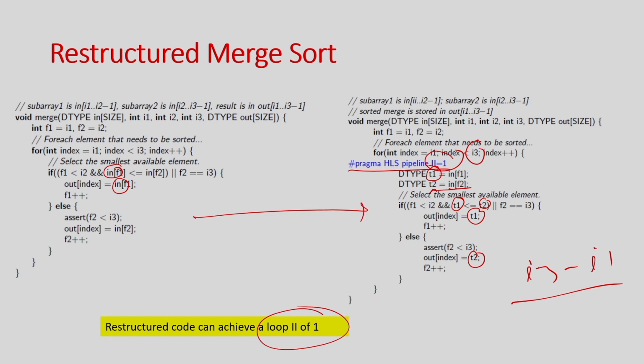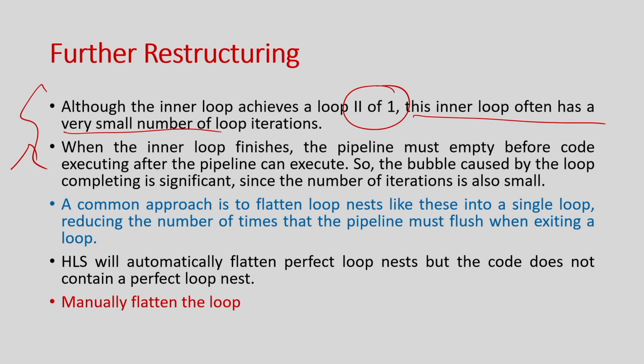So, you won't literally see the benefits. It won't show you that; it just gives you a question mark on the minimum and maximum latency needed, because this is basically a data dependent loop. So, we actually enumerated three problems. First, pipeline does not help here. Second, it creates unnecessary overhead of flushing the pipeline. And third, the performance benefit is not visible here because of the data dependent loop.